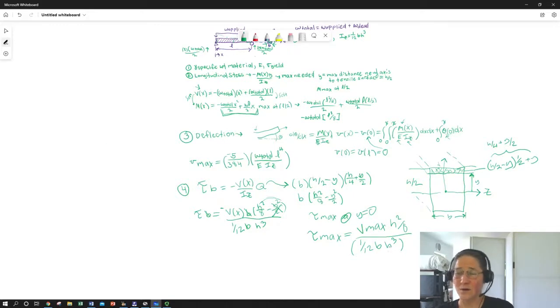So our shear will be linearly related to the beam height, the actual height, top of the beam to bottom. We didn't have that as much up here. In our longitudinal expression, if you look at our y halfway from the neutral axis to the top or bottom surface, you're going to have basically 1h. It'll cancel with one of the cubed h's.